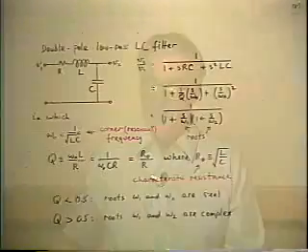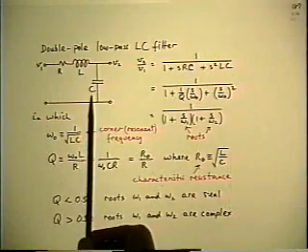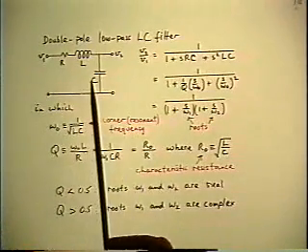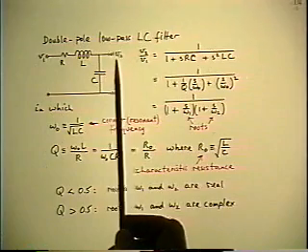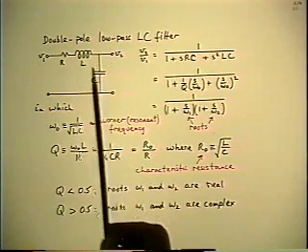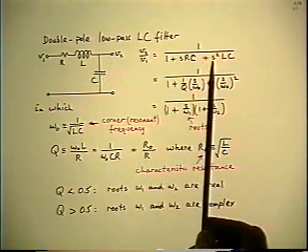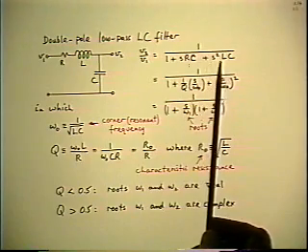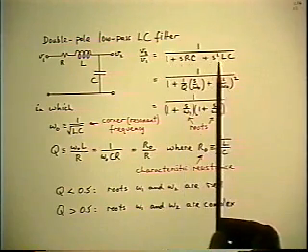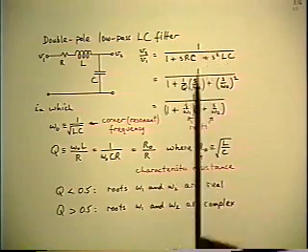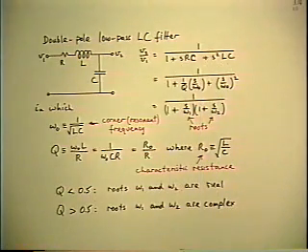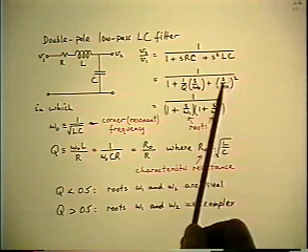We're talking about the basic RLC circuit, and the first thing we want to know about it is what is its voltage transfer function, V2 over V1. Treat it as a voltage divider, and in one line you get the basic expression, which is now a quadratic in complex frequency in the denominator, and the numerator remains 1. So now here's the first thing you do whenever you see a quadratic. You define a corner frequency and a Q factor.